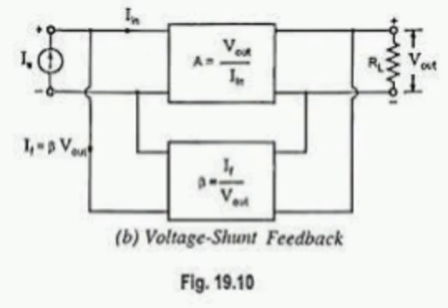Current shunt topology. Current amplifier: output is in series to beta and input is in shunt to beta. Beta has no unit, it stabilizes the current gain of the amplifier. Example: cascading amplifier. For different feedback configurations, the effect on input and output impedance and gain.